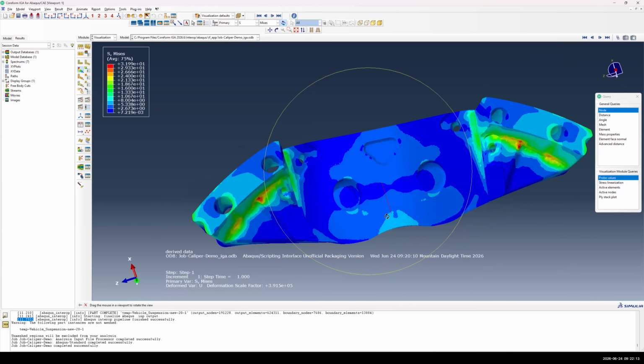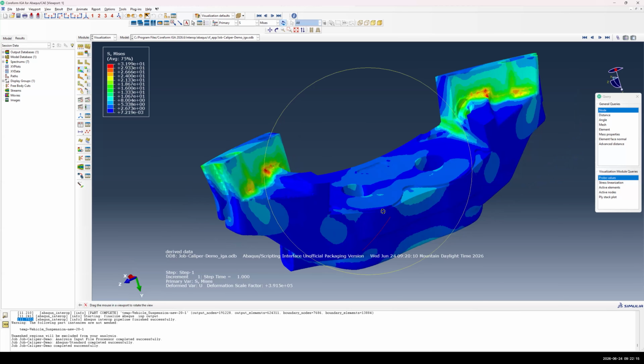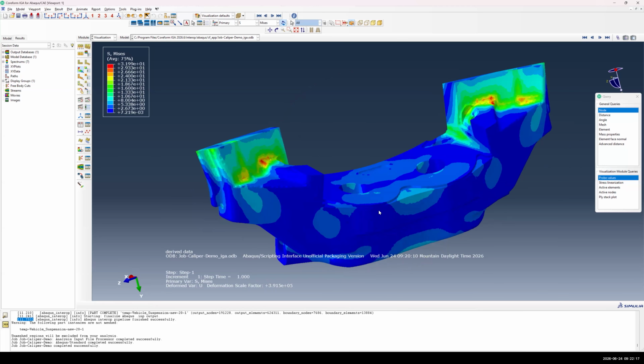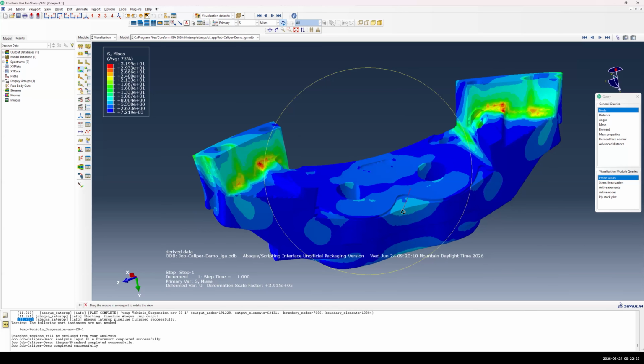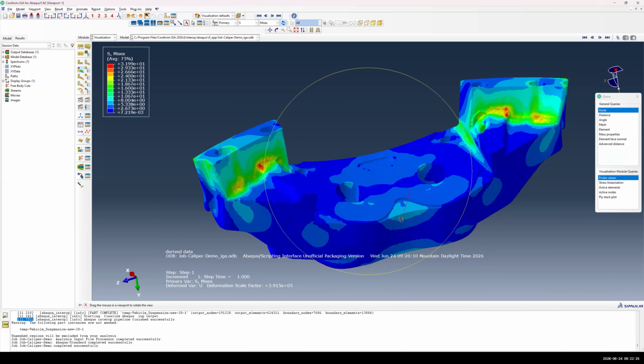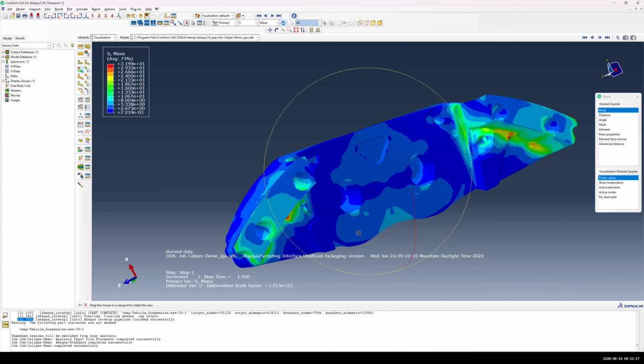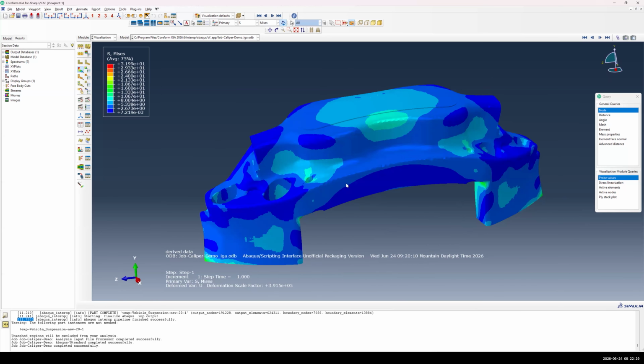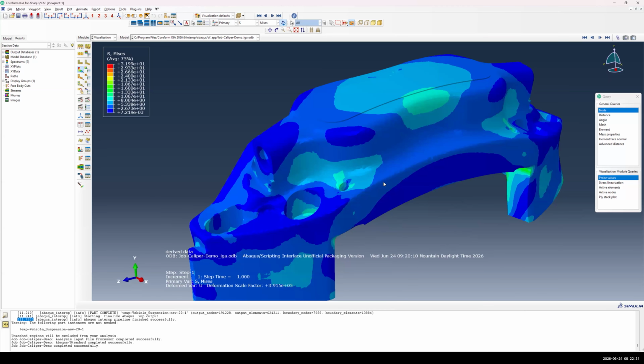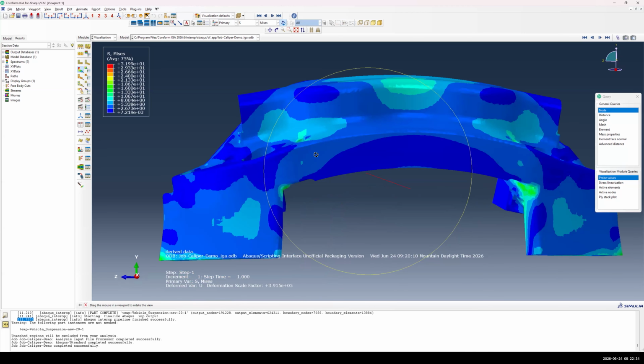And so here we're looking at the results again on this tetrahedral mesh. So it's really not exactly on the CAD in this case for visualization purposes, but rather on this TET mesh approximation of the results. But you can make out that we have all of our fillets. They're all captured by this TET mesh.